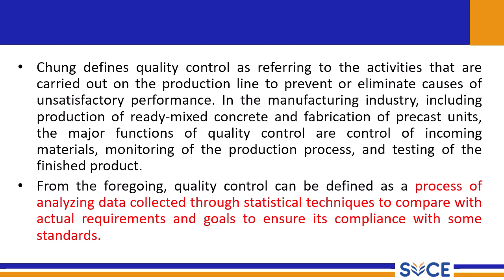In the manufacturing industry, including production of ready-mix concrete and the fabrication of precast units, the major functions of quality control are control of incoming materials, monitoring of the production process, and testing of the finished product. From the foregoing, quality control can be defined as a process of analyzing data collected through statistical techniques to compare with actual requirements and goals to ensure compliance with some standards.